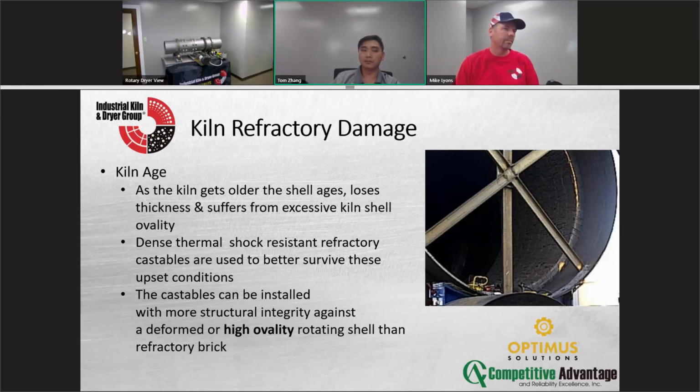Here's a question. What is the recommended heat up and cool down duration? Typically on most of the kilns it's 24 to 48 hours. The past 5 companies I've chatted with have been more on the 48-hour side: 48 to heat up and 48 to cool down.